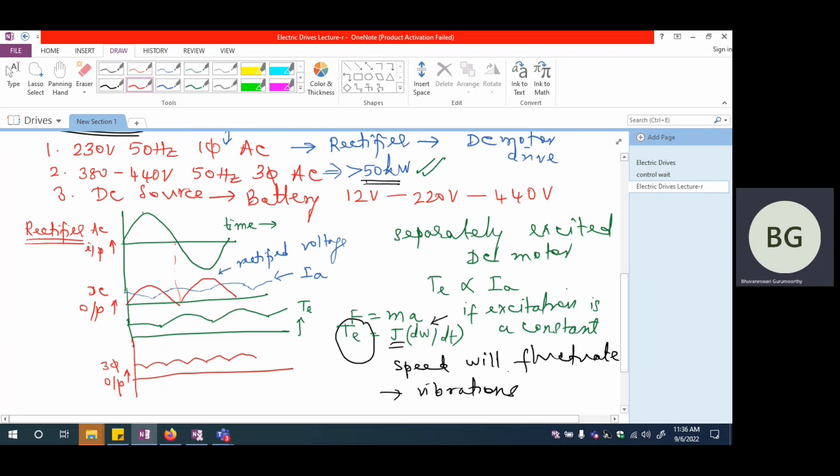Because of which, if you look at the oscillation here in the single phase case, the oscillation is equal to whatever is the peak value of the voltage. If the peak value of voltage is Vm, I'm going to have the peak value of the voltage as the complete ripple content that is present in the single phase output voltage. Whereas in this particular case, it will be much smaller than that. So the ripple is only this much in the case of a three-phase.